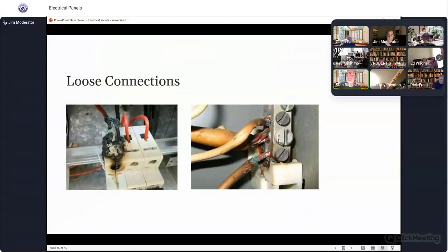probably that are creating problems there. Are there two wires on that big fat nut in the middle there? I think the screw's not in. That's what they're showing there. That's why it's loose. Yeah, it looks like it's kind of backed out there. So these are why we constantly hammer on these types of things, because they're small and seem insignificant, but in the electrical system, even a loose lug is a big issue. Right.